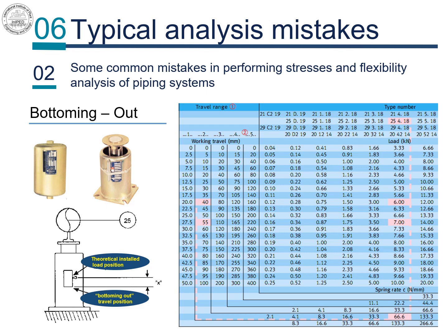The initial load, the so-called cold or installation load, is set on the spring to be 6 kN. In other words, after removing spring locks, when the pipe is already sitting on the spring which has been factory precompressed, it will release a reaction force on the pipe of 6 kN. This load will, according to stress analysis, keep the forces on the piping system in equilibrium, and the spring will be in its theoretical installed position.